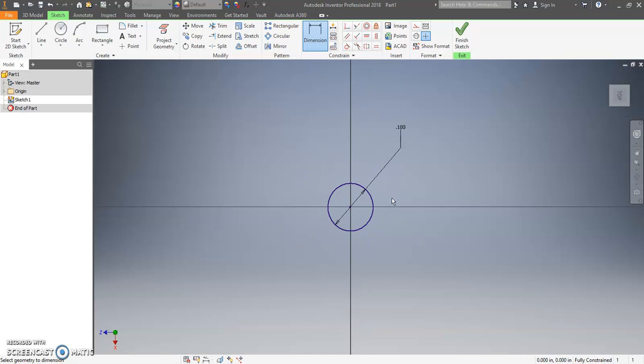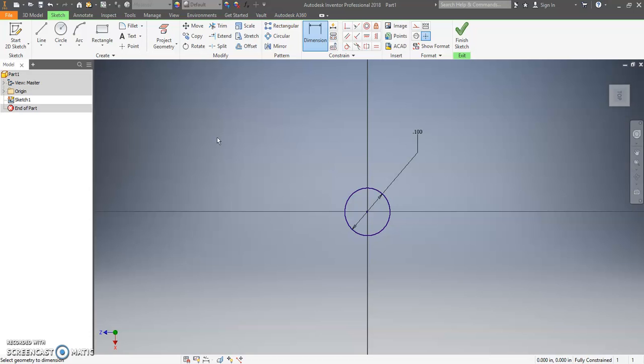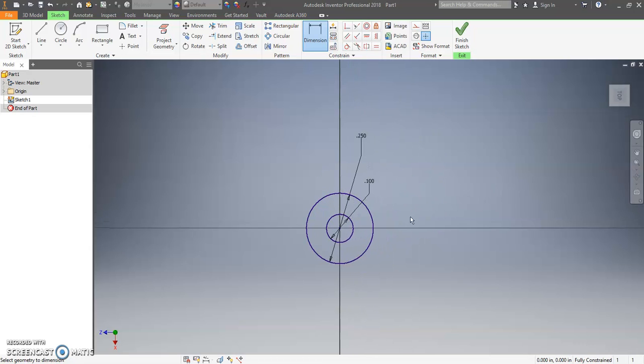We're going to zoom in a little bit and recenter it. Now that we have that first dimension, we want to make our circle for the outside diameter of the middle part of the piece. We right click, OK, and make it a diameter of 0.25 inches. That's going to make the middle part of our impeller about 1/8 inch thick, and that's what connects our fins together. So this outer circle is going to be 0.25 inches. We click OK and zoom out a little bit.